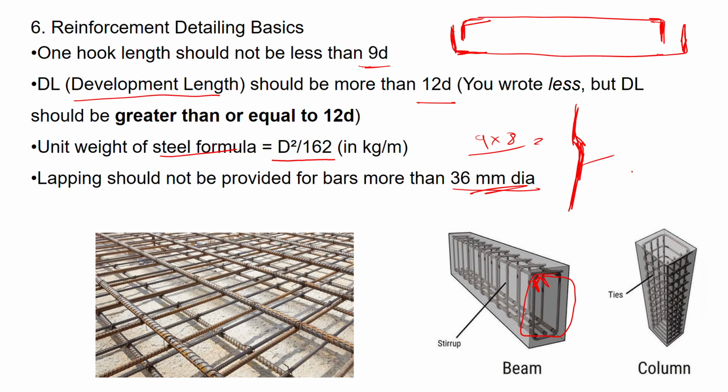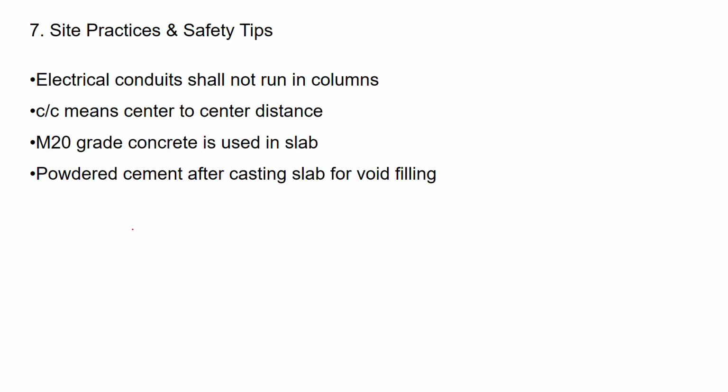Instead we are going with something called, what you call, joist. Sorry, not joist. We use couplers. Couplers will be like this. So we connect one reinforcement to the other reinforcement using this coupler. That is how it works.